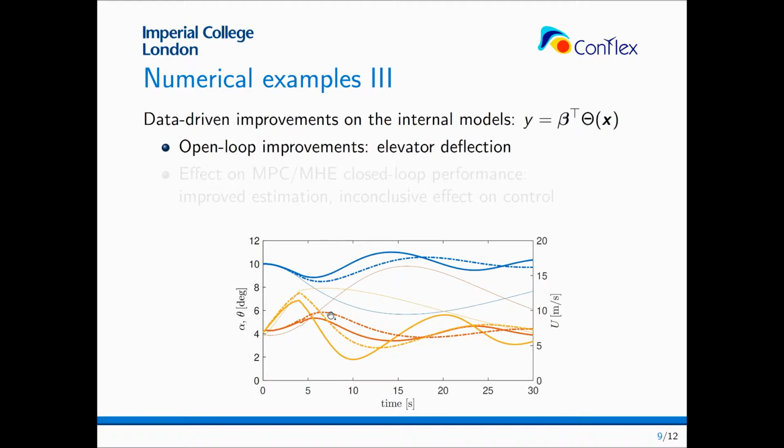That has been checked also with some other cases, where we see again that this dash-dotted line, which is the one with the data-driven additions, reduces the discrepancies, which are very high and very noticeable in our linear-based aerodynamics model. I mean, we still observe that there is some discrepancy, but we believe that this is caused by the modal truncation. So remember that at some point we decided to truncate our ansatz for the solution.